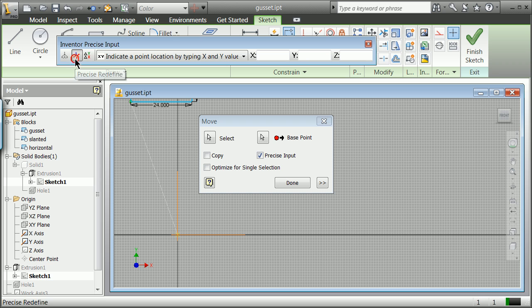So basically, very often we're going to use the delta or not. In this case, I'll turn off the delta, and I am going to once again pick my base point there. I'm in my delta, so I can change my X to maybe 100. Once again, forget to turn on the keyboard. Sooner or later I'm going to get a keyboard so I don't have to do this each time, but when this is clicked on I have the ability to give deltas, and in this case deltas are going to be the same as absolutes because we're still going from 0, 0.